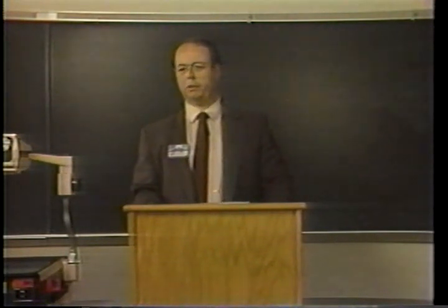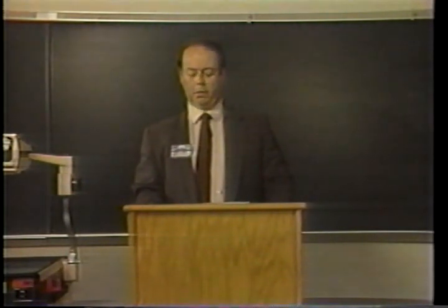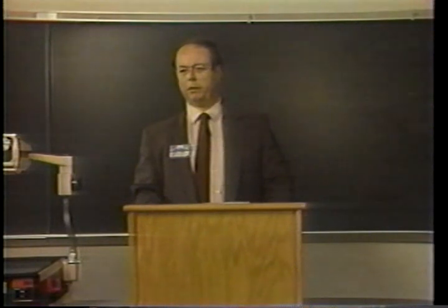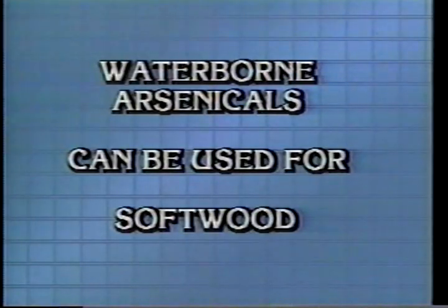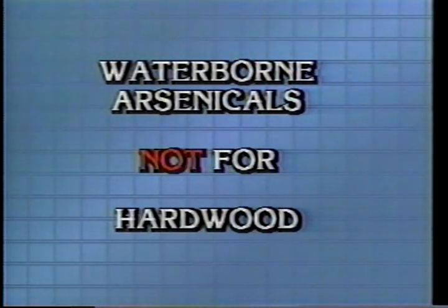This is both creosote and oil in penta. And these preservative products should be used for hardwoods and softwoods. It is further recommended that with respect to softwood materials the waterborne arsenicals could be used, but the waterborne arsenicals should not be used in the pressure treating of hardwoods.